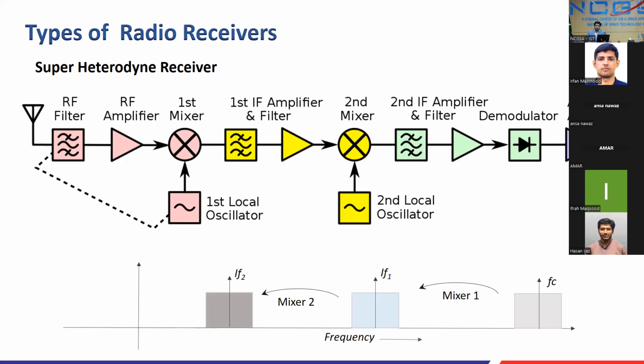That also depends on which application you are targeting. That system is mainly for communication intelligence application. We are not interested much in the frequency shift. You are more interested in the data, because in a communication signal there is a lot of data modulation, digital bits, PSK, ASK, QPSK, QAM. So there will be a different requirement for the ADC for this model.